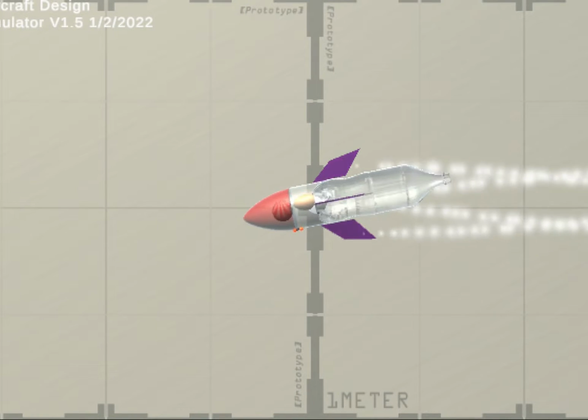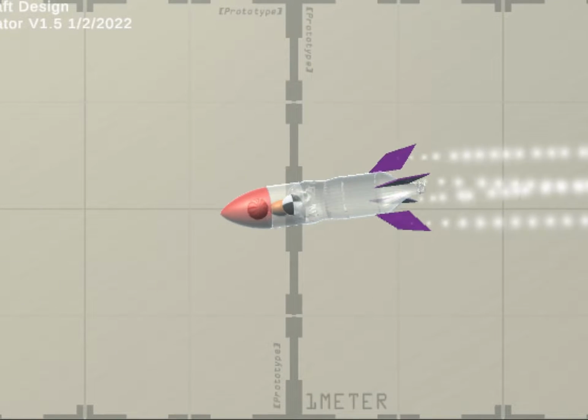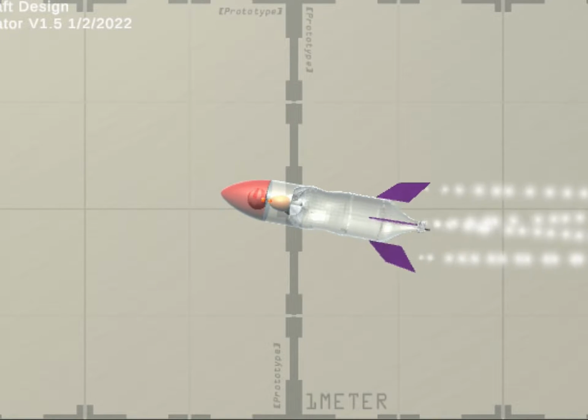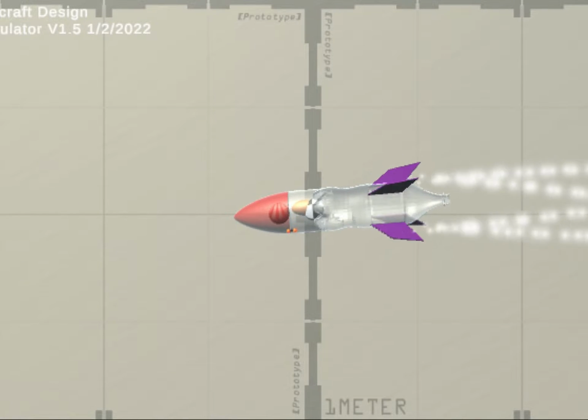With the help of simulation software, we can optimize a rocket to meet the design criteria by making adjustments to the fin position, shape, and number of fins along with the shape of the nose cone. It is important to have a stable rocket to ensure it has both a controlled climb and descent. Making changes to these parameters helps you to make an informed decision and make multiple versions of your rocket, each better than the last.